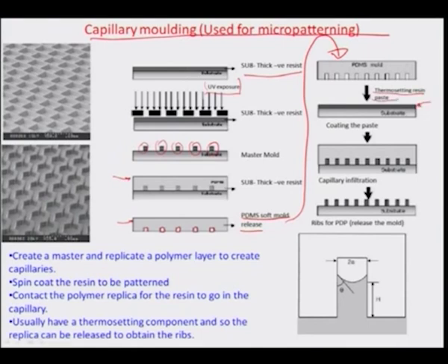And here, for example, when you pressurize this PDMS mold on the top of this thermosetting resin, the resin would go inside these cavities and fill up, although they may not fill up completely. There is a downside to this process, and I will illustrate a little bit later. But the idea is that when these capillaries are molding the thermosetting resin paste, and then temperature is taken up, so the T is increased at this particular step.